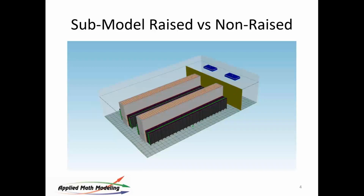And the reason that is done is to try to unify the flow across this section in case one of these units is off. So in the N+1 case, when you're only using a certain number of these units, you'll get a very different airflow pattern. And that's an important case to study because it will dramatically affect the cooling in the room.